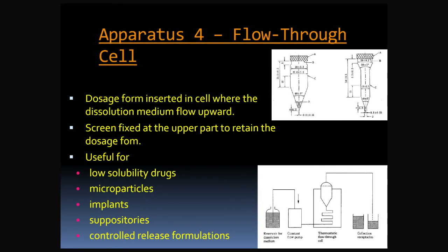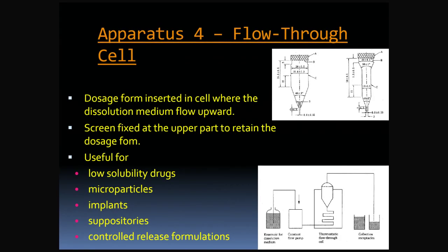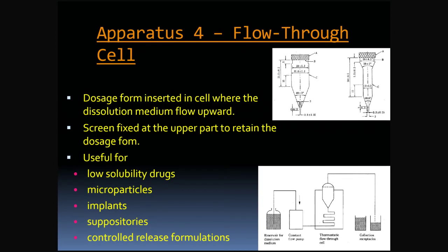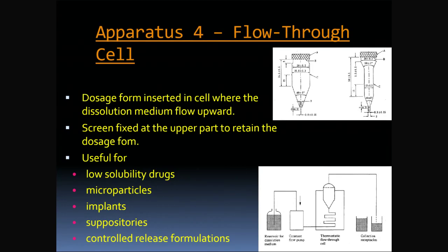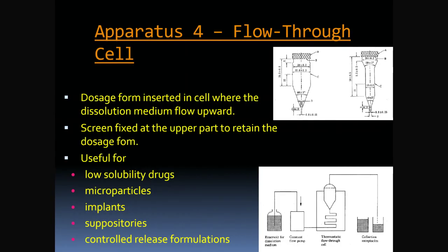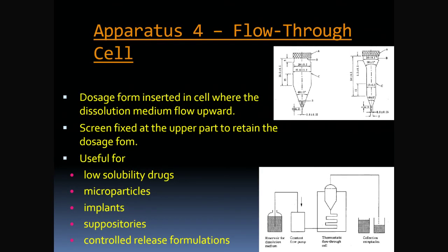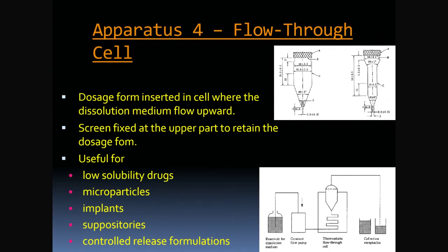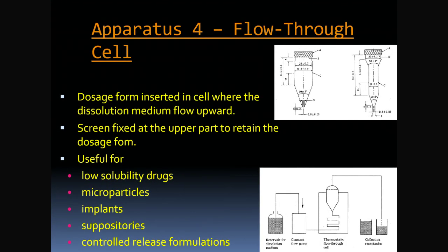This open-loop architecture is scientifically superior for low-solubility drugs because the constant introduction of fresh solvent prevents the bulk concentration from rising, thereby maintaining a maximal concentration gradient between the solid surface and the fluid. Observe the precise internal dimensions in the technical drawing, such as the 22.6 millimeter diameter. These fixed geometries, combined with the pump's volumetric flow rate, dictate the linear velocity and Reynolds number of the solvent as it interacts with microparticles or implants.